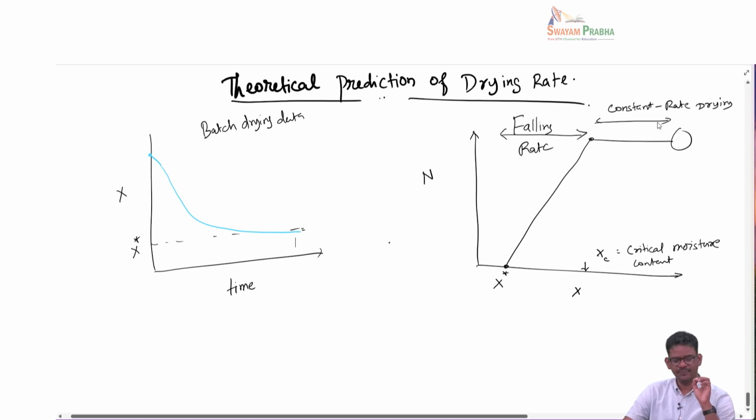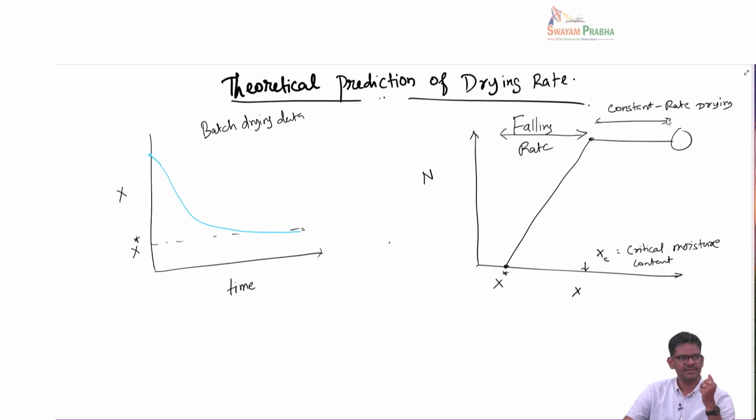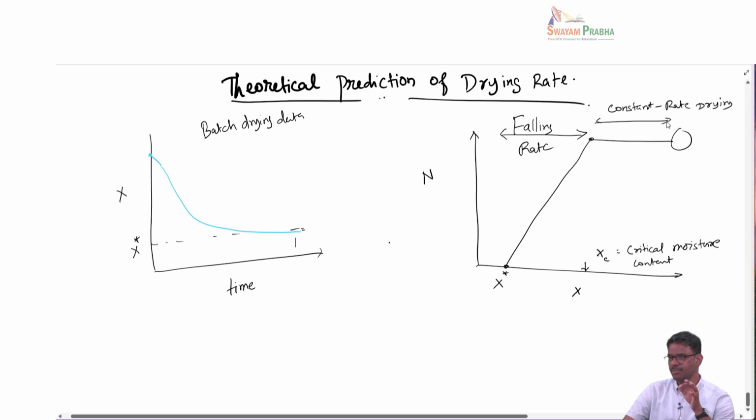On the other hand, constant rate drying relates to drying of unbound moisture. What is unbound moisture? Unbound moisture is water that is on the external surface of the solid matter. It typically forms a thin film and acts like pure water. The vapor pressure exerted by the unbound moisture is equal to that of pure water. It is as if a thin water layer is evaporating, so here the solid is not playing much of a role, it is not really controlling anything.